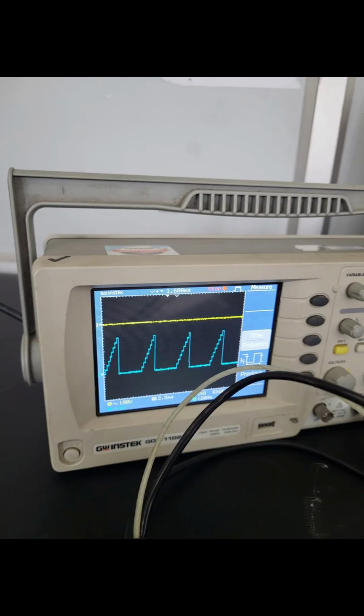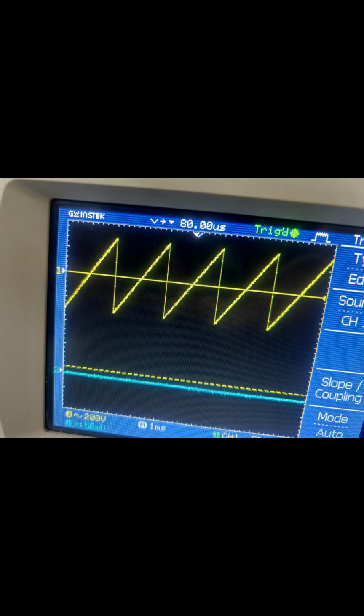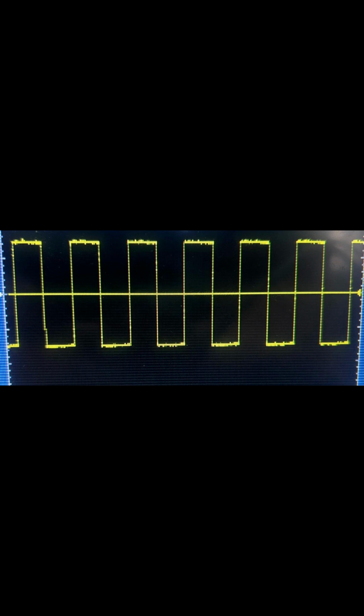On the oscilloscope screen, we can clearly observe the generated waveform. When the program increments data continuously, we see a ramp. When stored weights are used, we observe a stepped sawtooth pattern, and when the program alternates between 00 and FF, we see a rectangular or square waveform.